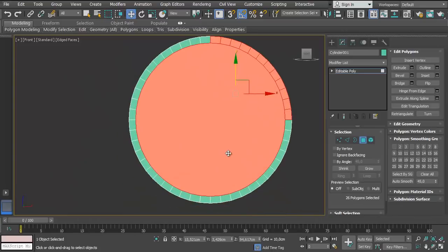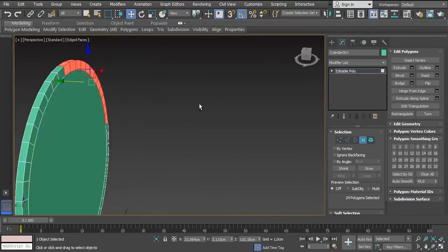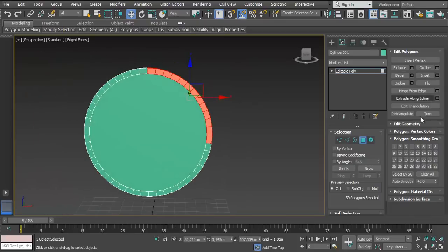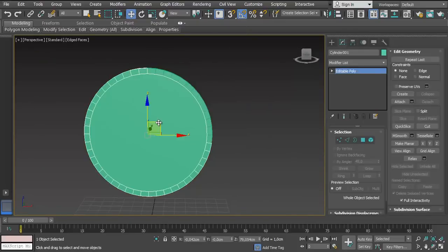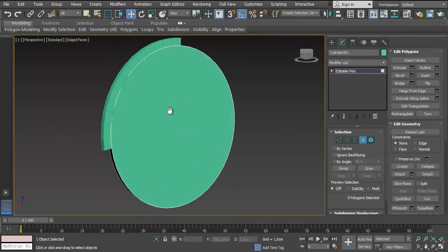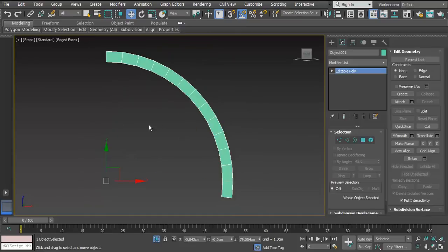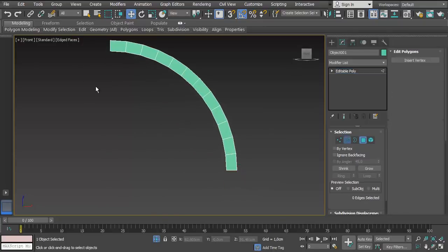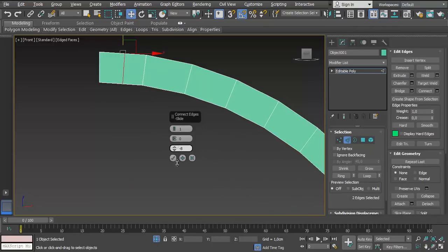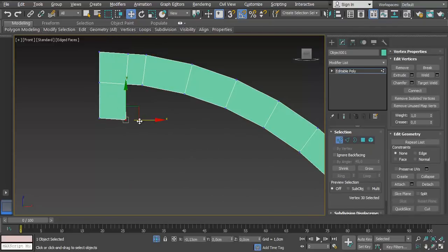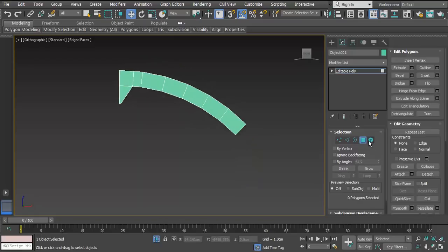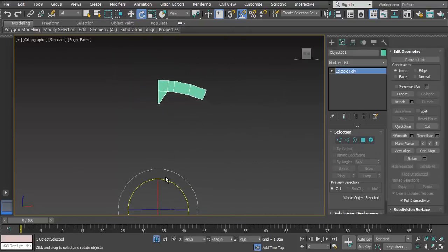Okay, the first thing I'm gonna do here is get rid of most of this cylinder we created, because we want to take care of the outer edge, or the rim, of the shield. We're gonna only work with a small portion of it, then replicate and copy it all over to get that rim back once again. This is gonna allow us to avoid repetition and create something very accurate. So we're gonna keep removing these parts until we get to this point here.